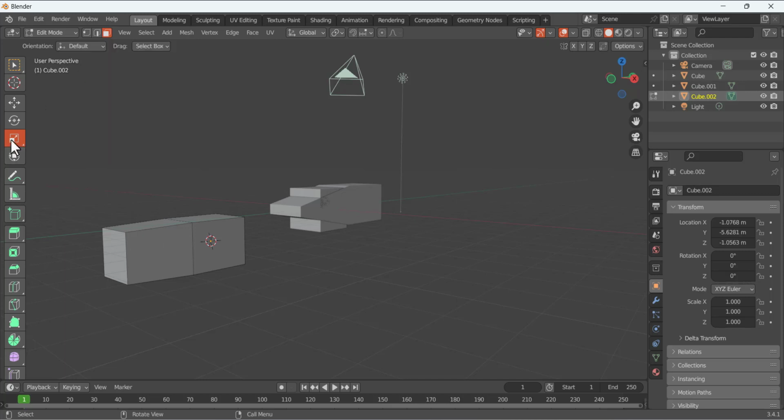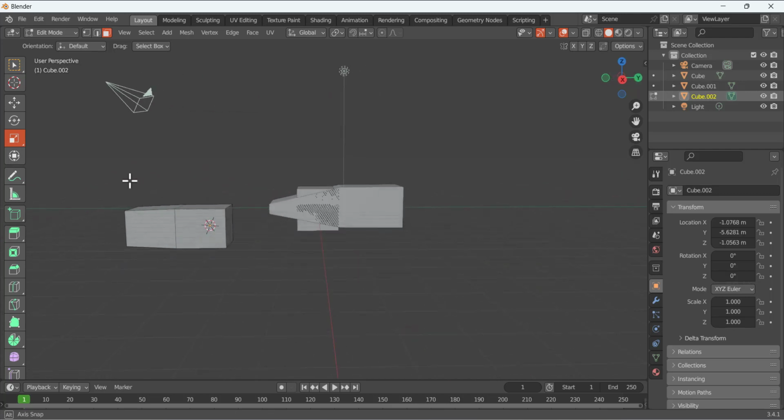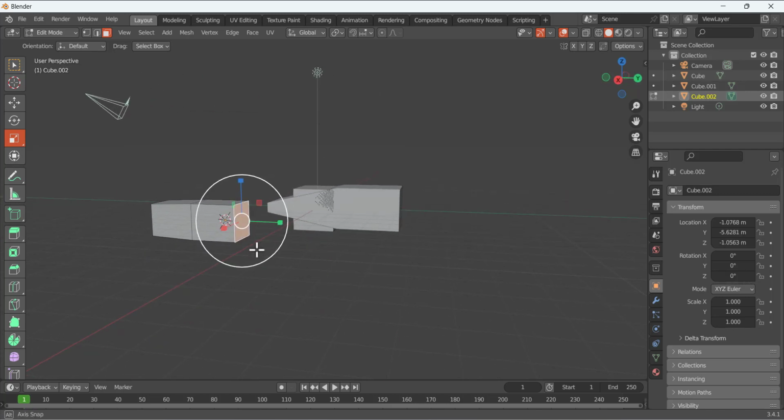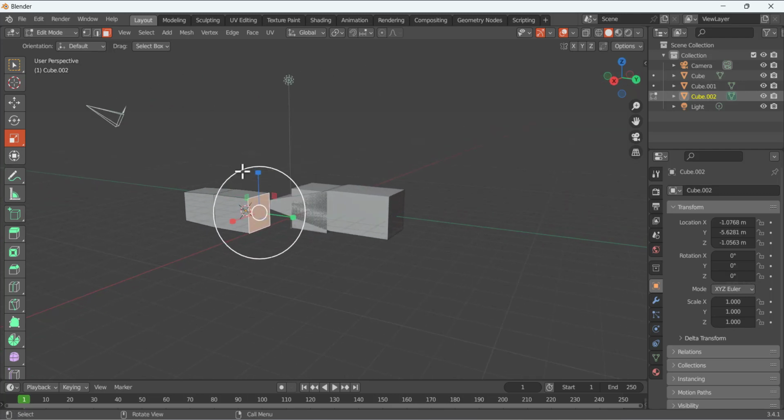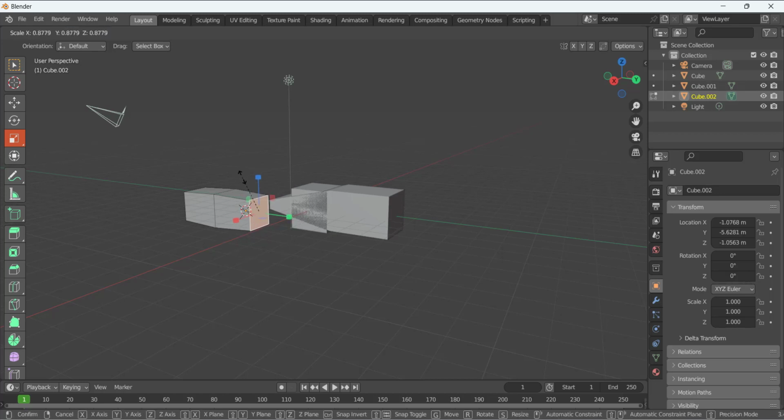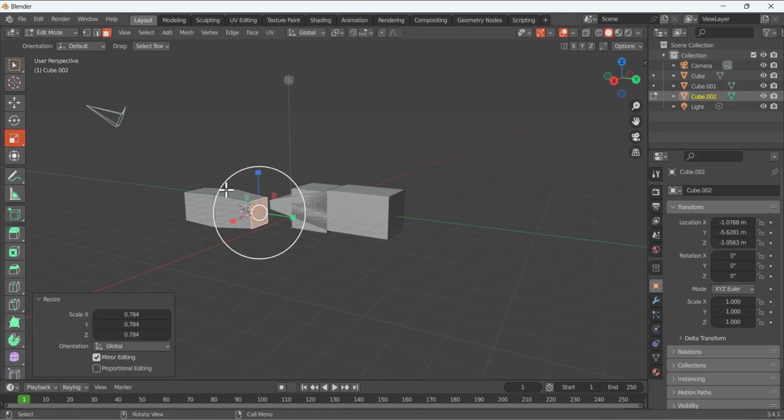Again, face is selected, selection mode is face, and the scale is selected. We selected this other side, and the same way, this white circle, this bigger circle, we can click on it and then drag your mouse to rescale this face. And how much are we going to use? Same 0.9, 0.9, and also 0.9. So we type 0.9 three times.